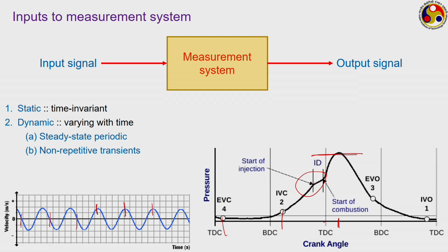So, this is the period over which the ignition, that is a spark plug in case of a petrol engine, or injection in case of a diesel engine, is done somewhere here, but the combustion reactions will start only at this particular point because of some pre-combustion reactions which may go on over this period. Now, if we talk about this particular cycle, it is not of a periodic nature, it is very much an aperiodic variation over one cycle.